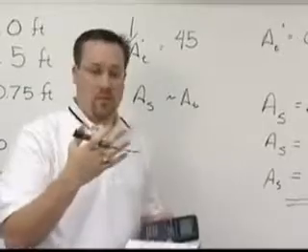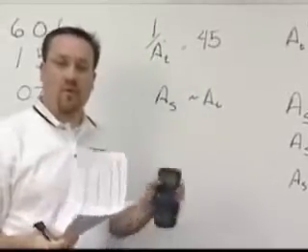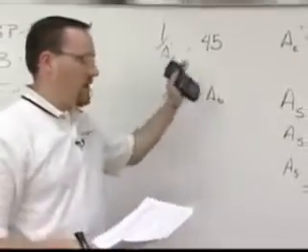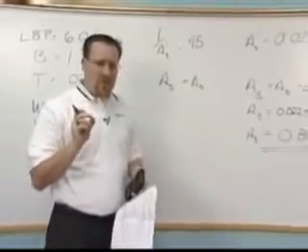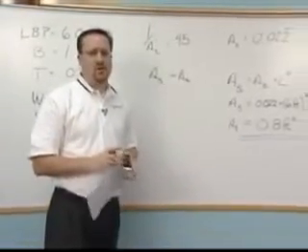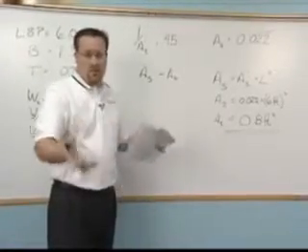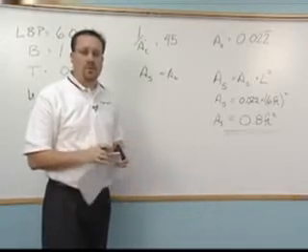Now that's a pretty big rudder, all right? But you'll notice that this rudder was sized for the best maneuvering for this type of block coefficient. You have to realize that all of these types of equations are just approximations. The hull design is actually going to be pretty important to how you maneuver as well. So you can't take this to the bank that if you have this rudder area, you're going to do this particular maneuver. But it's a good rule of thumb, and I think it will help you do your design.